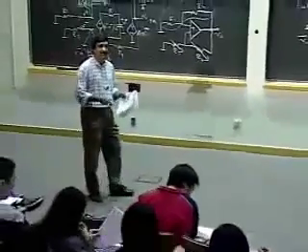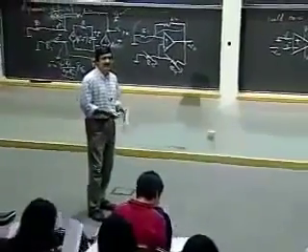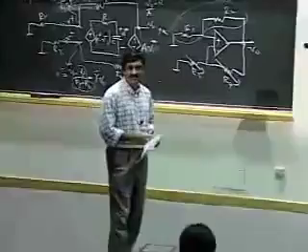Notice how the output switches at plus 6 volts, and then switches at minus 6 volts to plus 12 or minus 12. That's a hysteresis property. And we can actually use this property to build a clock circuit, which is on page 9. It builds an oscillator that sits there and oscillates by itself. And you will see details of that in recitation tomorrow.